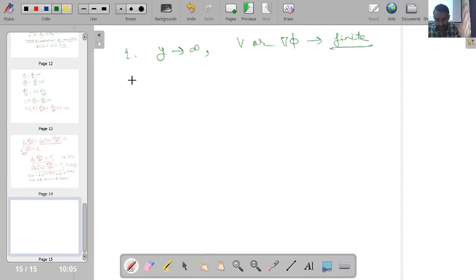Then another point is if I calculate the slope at the wall. So dy_w by dx, that is nothing but my slope at the wall. The slope at the wall will be equal to v_yw dash, the component of perturbation velocity in the y direction, divided by v infinity plus v_xw dash from our previous theory.